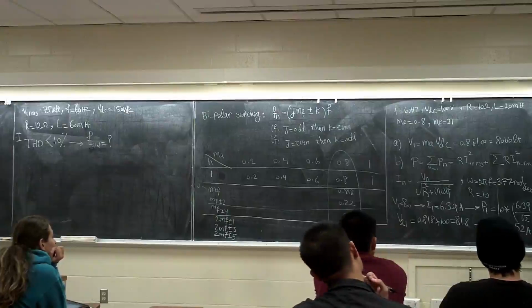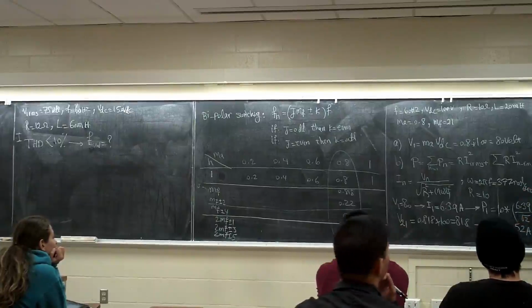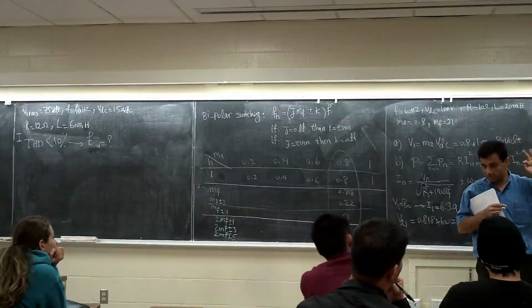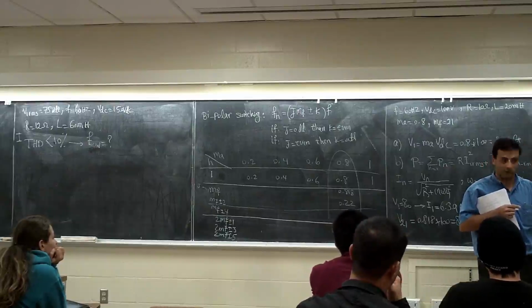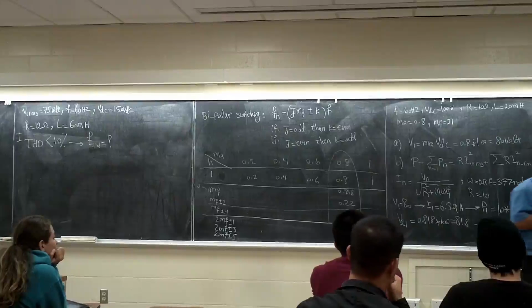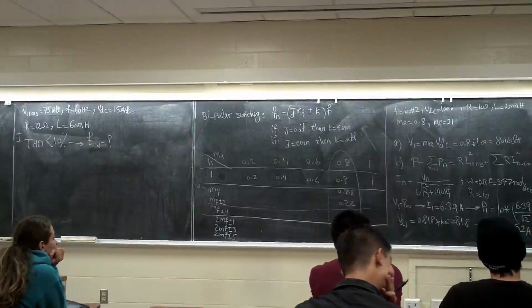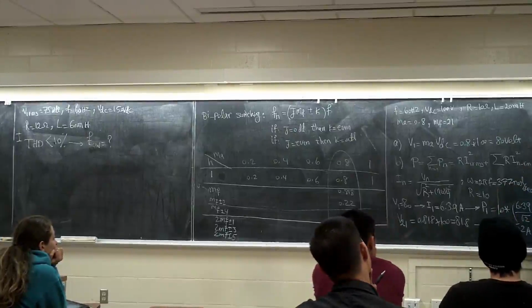So this is bad, what I'm doing here, so be careful. If I go just with this one, THD is going to be a little bit smaller. Maybe instead of 8.7 it would be 8.2. Keep this in mind. The number I'm calculating is a little bit better than what it should be, but I will compensate for this one later. So I know how much my I1 is, I get rid of all the rest, and I know how much THD I want.